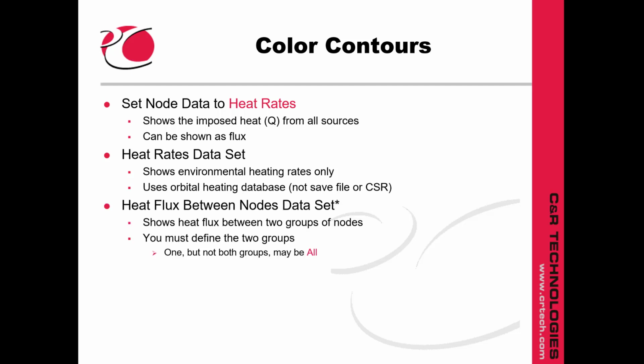You can also set heat flux between nodes. Show heat flux between two groups of nodes. You must define the two groups. One, but not both groups, may be set to all.